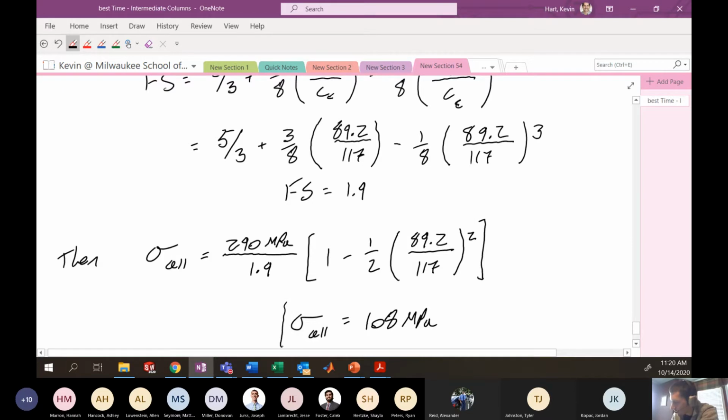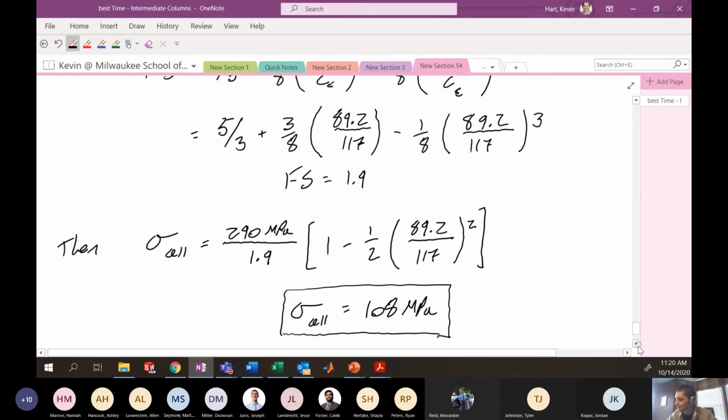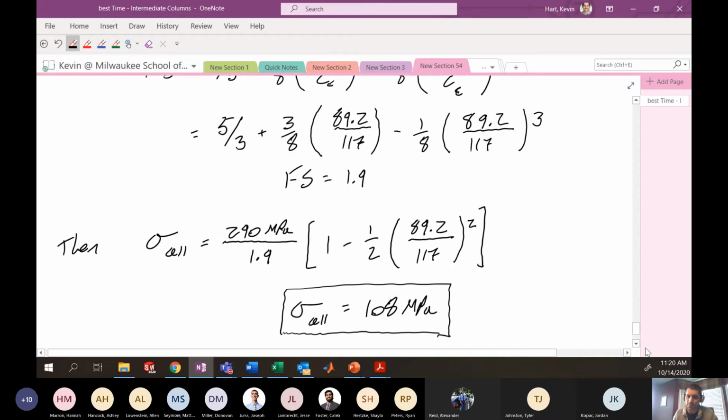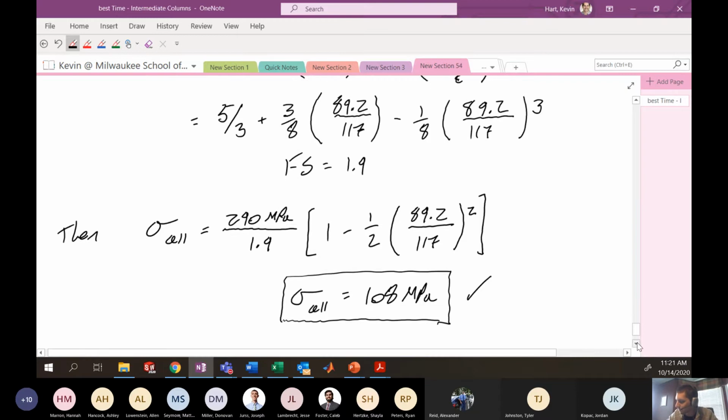Okay. So this is 1/2 of our allowable stress method formulation. We've calculated the allowable stress that this particular cross-section can handle before it fails by buckling. Notice, we have not talked at all yet about the eccentric load on the structure. We haven't said anything about that load P. This is only based on the geometry and the material properties of this cross-section, the yield stress and the elastic modulus. So here we are, this is my allowable stress.